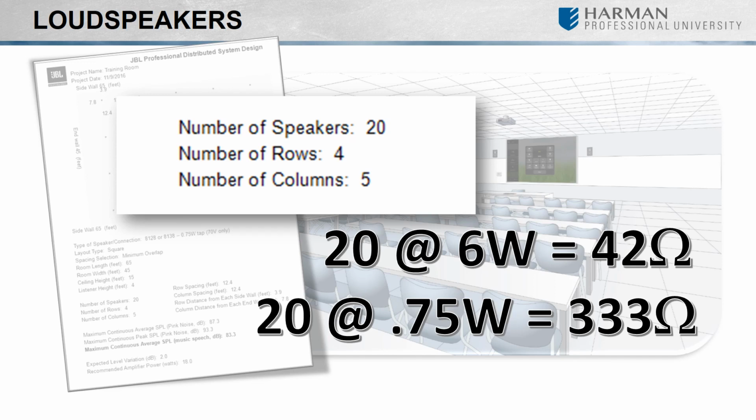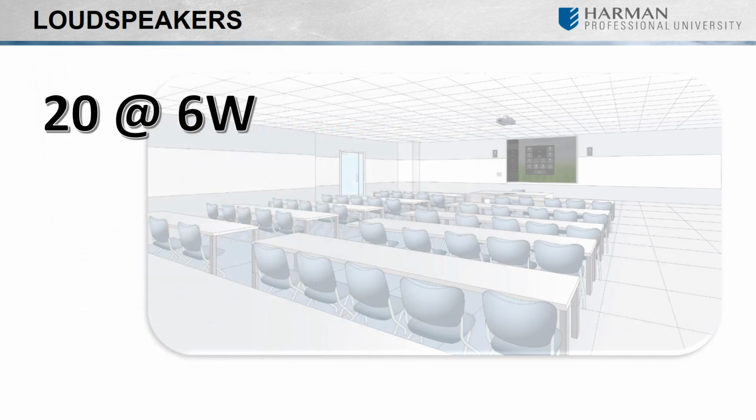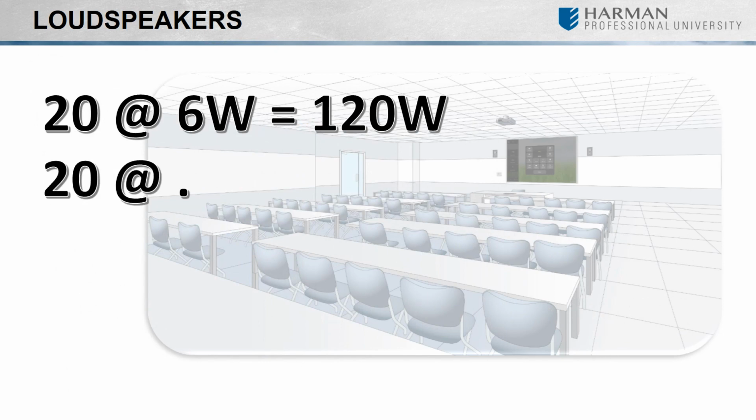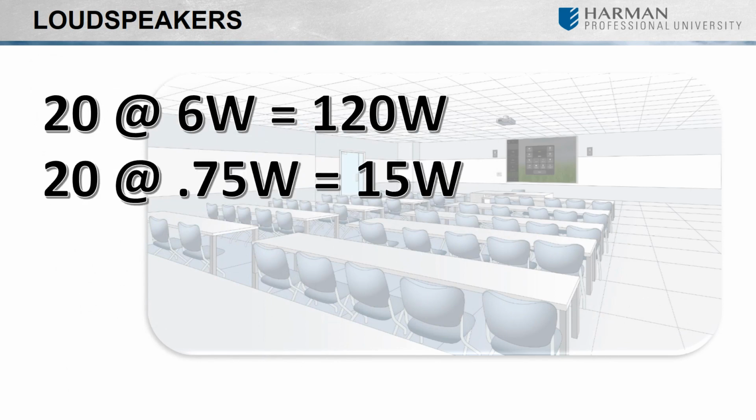These values were found using Ohm's law. We'll get more into those calculations in the instructor-led class. And what about power draw? Well, 20 speakers at 6 watts each will be 120 watts, while 20 speakers at 0.75 watts will be a small 15 watts total.